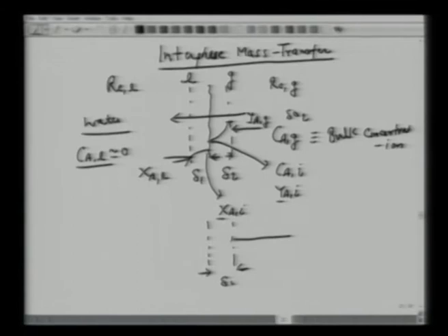So concentration drops. Let's not worry about whether it's linear or there's some profile, because ultimately we are going to work on this concentration drop from here to here. Film theory of course will say that the concentration within the film is linear. So now we have four levels. One is bulk, y_AG, then y_Ai, and now we have the liquid phase concentration, which is x_Ai, and then it drops across another resistance here before we have the bulk concentration x_A in the liquid phase.